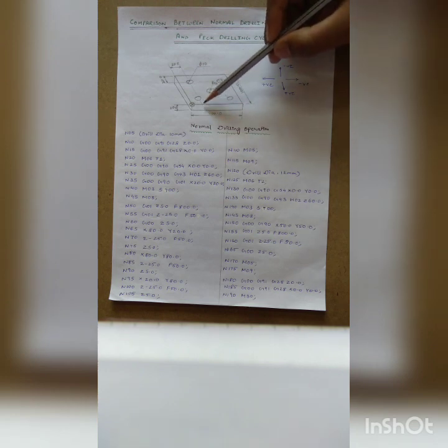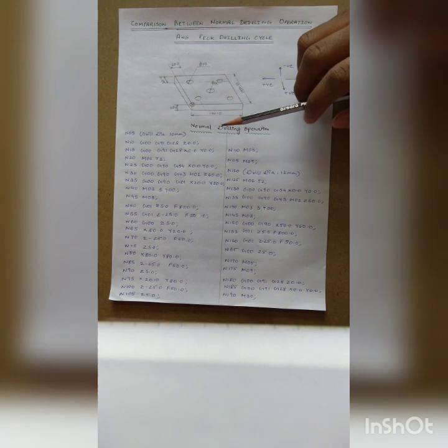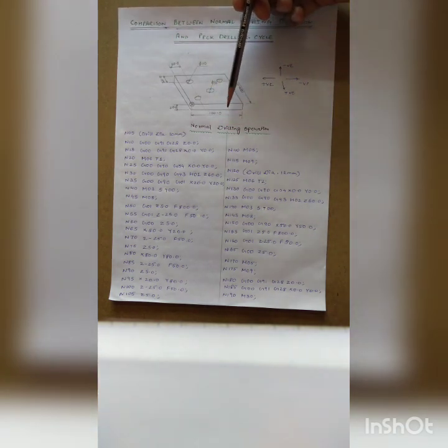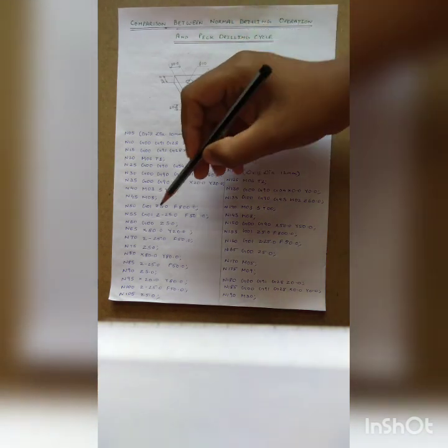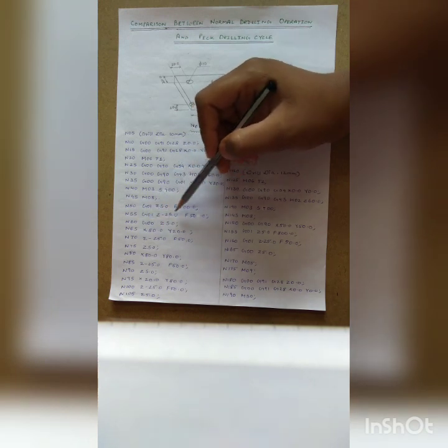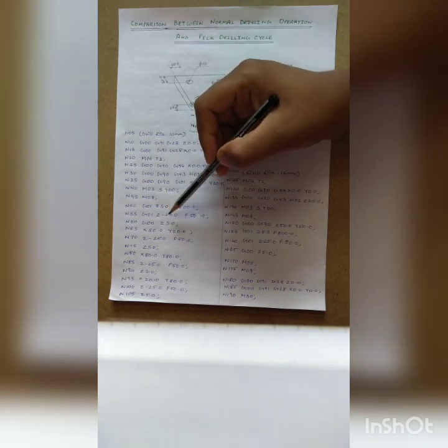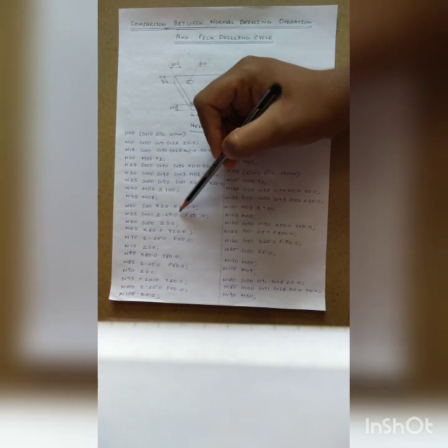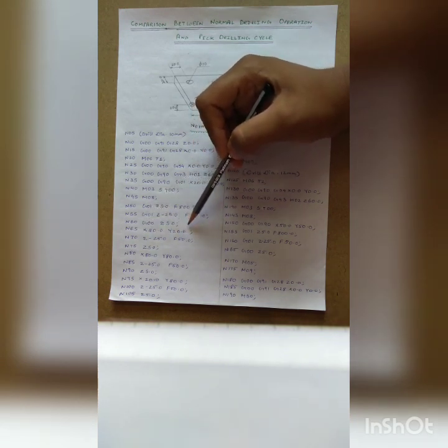As we see in the diagram, the height of the workpiece is 20 mm. So we have to insert the drill bit more than 20 mm for the proper finishing of the holes drilled. So we took Z minus 25 with the feed of 50. Then after that, the return to reference position.